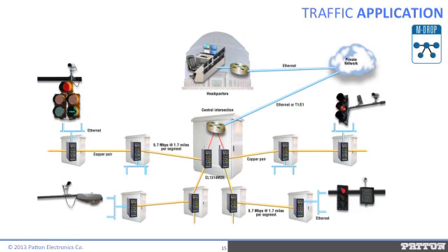MDE Ethernet extender. It was an integrated 4-port Ethernet switch, allowing me to interconnect IP-enabled cameras, controllers, and sensors with an IP router installed in the equipment cabinet in one of our main central intersections. The MDE has 2 LAN ports that interconnect neighboring intersections over our existing copper infrastructure. At the last hop, we would use Patton's ruggedized long-range CL1340R to terminate the final Ethernet segment operating over the legacy copper cable. With the MDE installed at each central intersection, our old closed-loop system is now IP-enabled, interconnecting all traffic signals, cameras, sensors, and controllers.